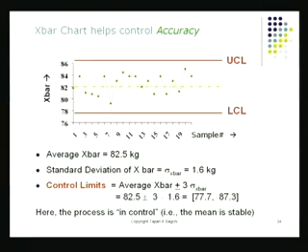Let's try to see what else we do. So we've got these formulas here. Let's work with some real data. The first thing I have to do is set up the system in place. So I set up the x-axis, which is going to be your sample numbers, and I set up the y-axis, which is going to be your X-bar values. But I need something more. I need the upper and lower control limits. These are statistical limits. These are ranges that define the natural variation of the process.